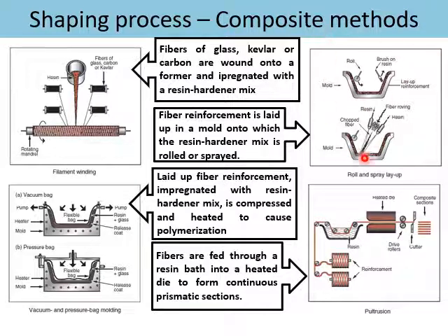Here is the advanced version, where the fiber and resin are sprayed on the mold and then rolled using a roller as a layup process. For high-tech composites, vacuum bagging is used to remove the excess resin so that you get the optimum fiber to resin ratio, such as in making aerospace components. Last but not least is the pultrusion method to produce composite sections.